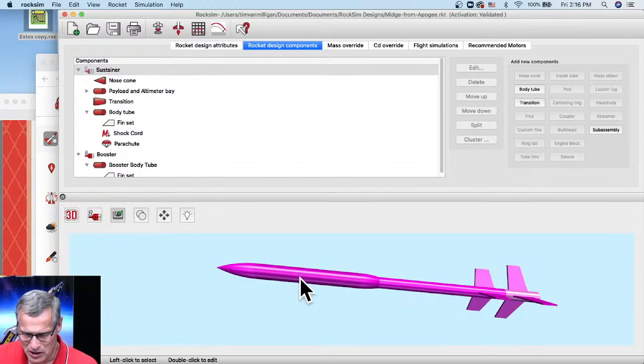So inside of here, you'd put a payload, which weighs 1 ounce, or about 28 grams. Plus, you put an altimeter in it to measure the altitude, and then you launch it as high as you can. This is a good event to use a piston launcher. And this one is designed as a 2-stage, but we can fly it as a single stage. Okay, so we want to fly this comparing an A3 versus an A3 with a piston on it.